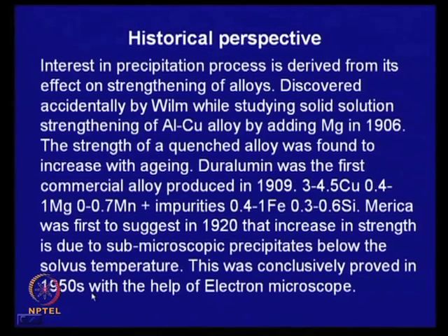And thereafter there has been considerable work in this area, and we will see how we can control the process of precipitation in this unstable terminal solid solution to get the maximum amount of strengthening. And we will see how that extent of strengthening will be controlled by controlling the phase transformation or precipitation process in this alloy.